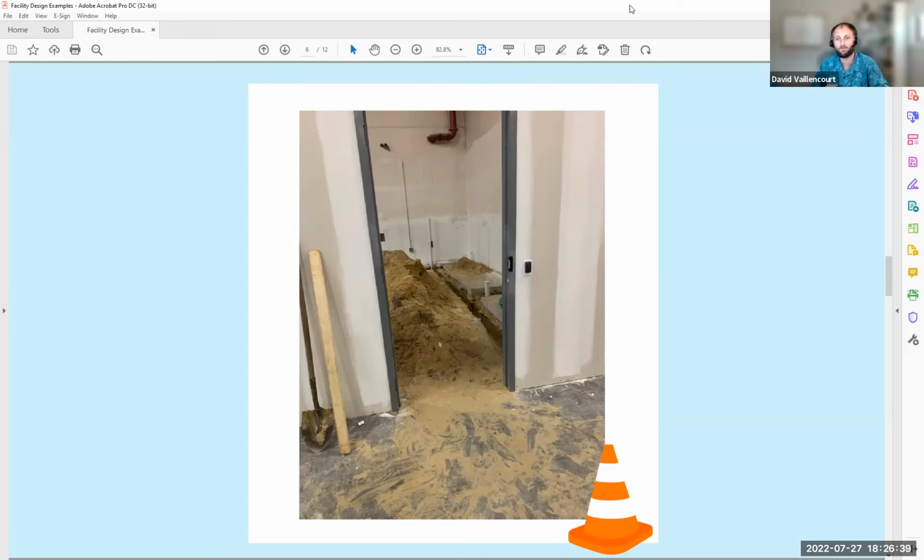I don't know if David or Brian, you have anything to add to that, or examples where you've seen something similar, unintended. We have a lot of renovations in this sector, and getting knowledge of what is going on under slab and how you need to worry about slopes and how you need to worry about connecting to it, whether you trench that as they've done here, or whether you take up that entire slab. That usually requires hours of conversation and estimating. Sometimes you don't know, you have to run cameras down under slab drainage. There's a lot of things, but understanding what's going on under slab is one of your first challenges in looking at a building that you might want to renovate.